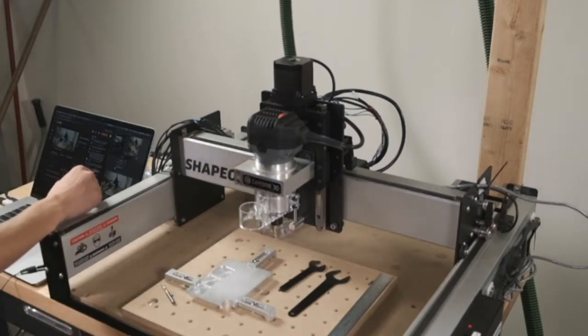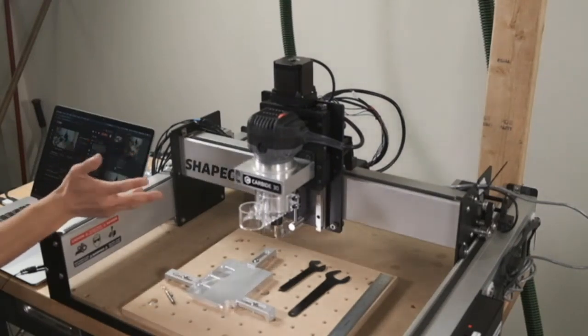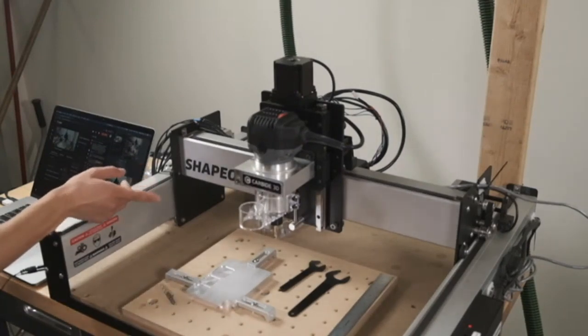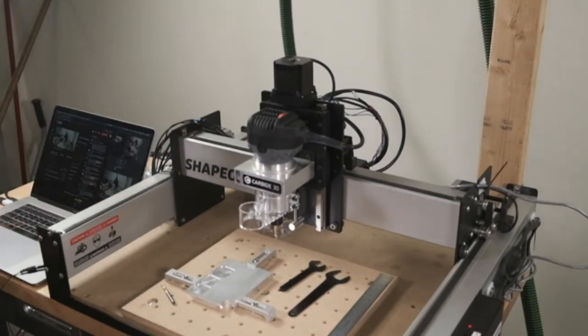iPad Pro as a controller, it would be interesting. The problem is Carbide Motion is not going to run on an iPad, and you also need to connect it to a regular USB port. There are third-party apps for running Grbl-based machines. Like you can run a Shapeoko off a Raspberry Pi. You just need something that will transmit G-code to the controller. As far as I know, there's nothing out there, but we don't plan on having an in-house solution for doing that.